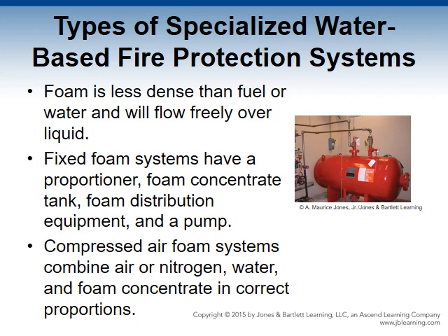Foam can be distributed subsurface, on the surface, into the side of a tank, overhead, or in a confined area. Subsurface injections occur inside cone roof fuel storage tanks. Application requirements determine the types of equipment used to protect a hazard. Equipment includes some of the following: an oscillating motor nozzle, a foam making chamber, sprinklers, nozzles, and foam generators.